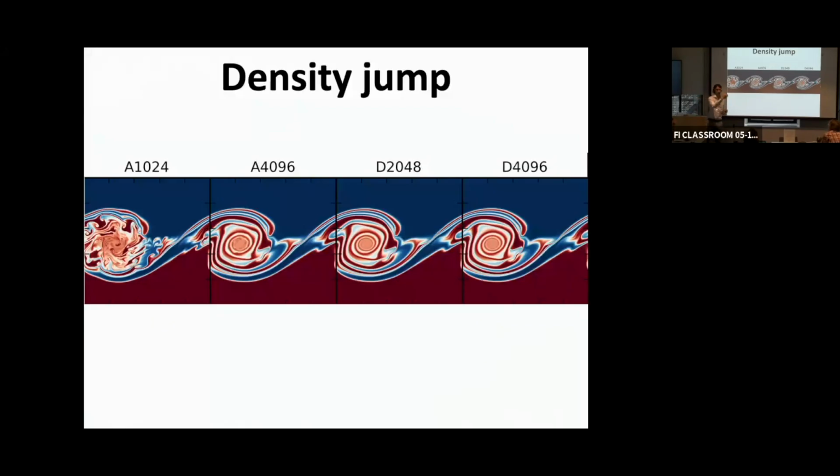If you're converging exponentially, sometimes going to higher resolution isn't helping you very much. And that's actually what we found here: in Daedalus, the largest source of error is not the spatial resolution; it was time stepping. So if you really wanted an even higher accuracy solution, you shouldn't increase the spatial resolution; just decrease your time step size.